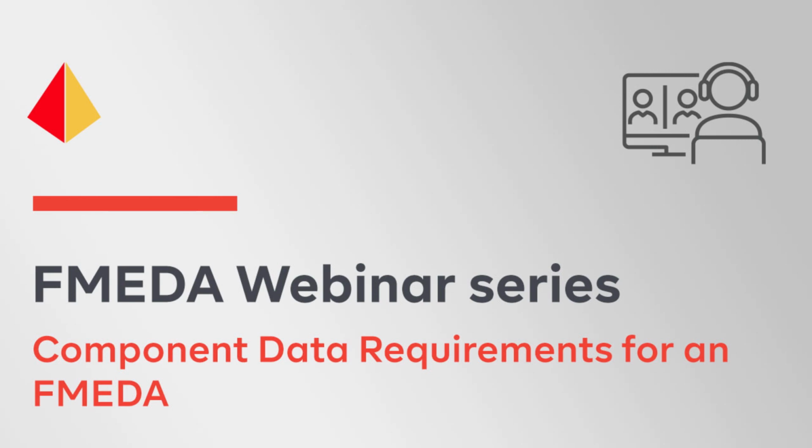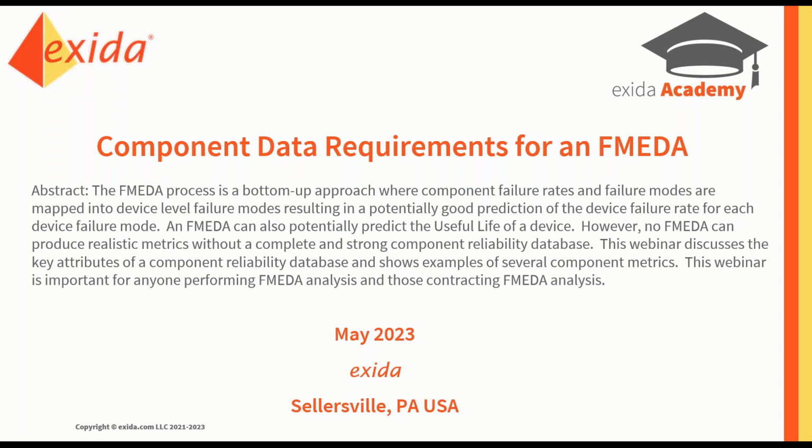So basically, within this webinar we're going to look at the key attributes of a component database, and we're going to show examples of several component metrics that you should be looking for in whatever database you decide to use. And of course, this database is the key element, the glue basically behind your FMEDA.